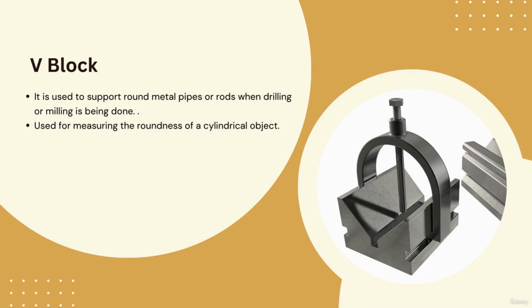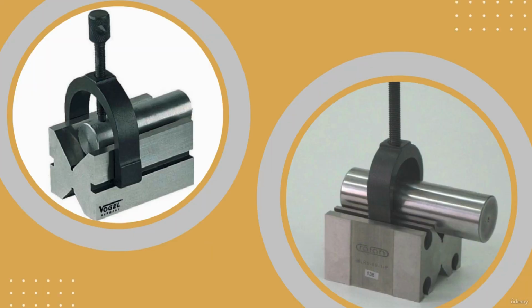It is nothing but a static measuring instrument. If you have a cylindrical component and you want to fix some of its locations, you cannot fix it on a flat surface, but you want to measure it, then you use this V block. Take your cylindrical component, either a shaft or some kind of part, and place it in these locations. You can know the difference of the surface by using a dial indicator. We can use a dial indicator to measure all the deviations. Only the holding surface and placing of the components differ.